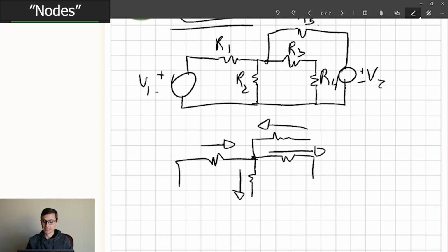That's occasionally possible if you've got, like, a charging capacitor situation. But that's only in transient conditions, not steady state. This is a steady state analysis, so that is simply not possible. You can't have a rate of change on your voltage in steady state. So that is why our net current is 0.